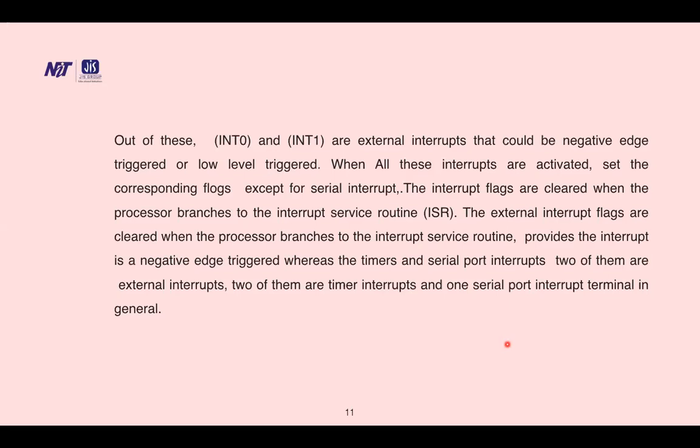Out of these, INT0 and INT1 are external interrupts that could be negative edge triggered or low level triggered. When all these input interrupts are activated, they set the corresponding flags except for the serial interrupt. The interrupt flags are cleared when the processor branches to the interrupt service routine, ISR.